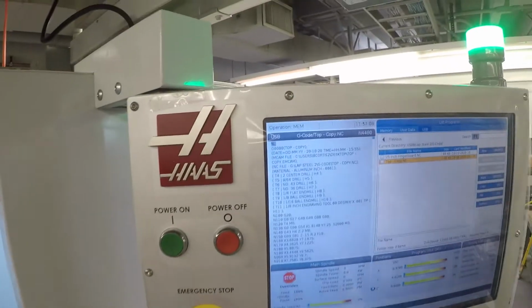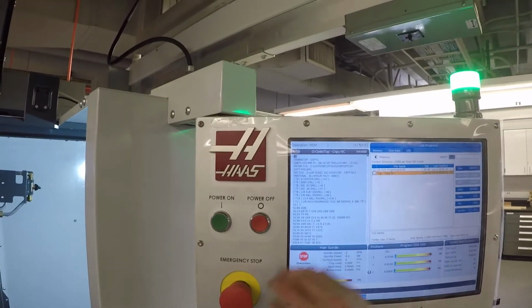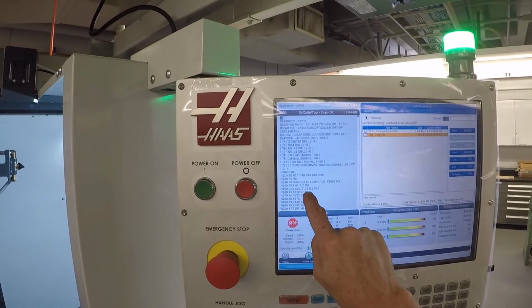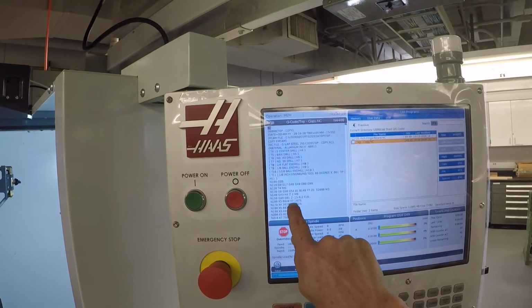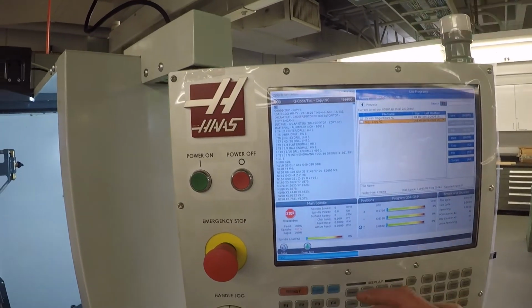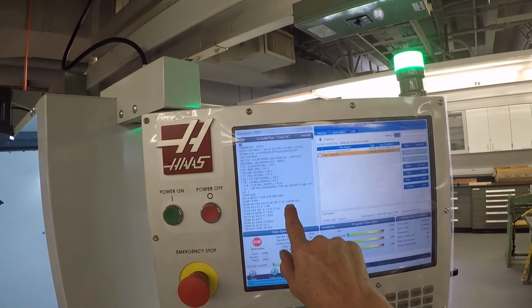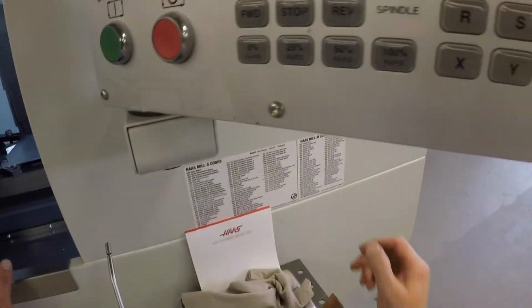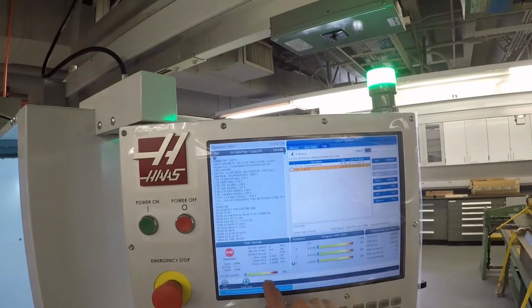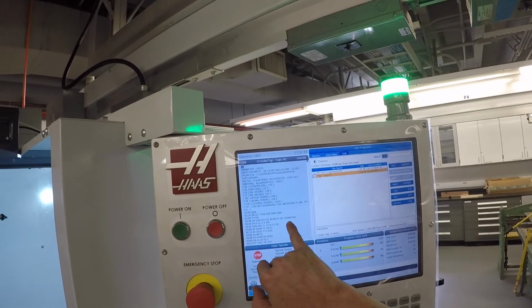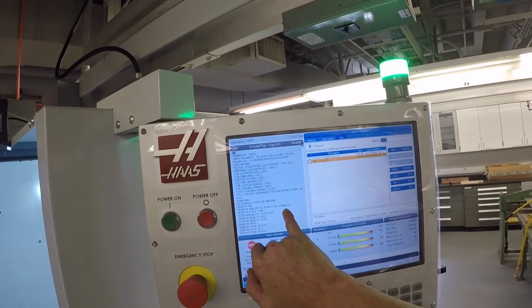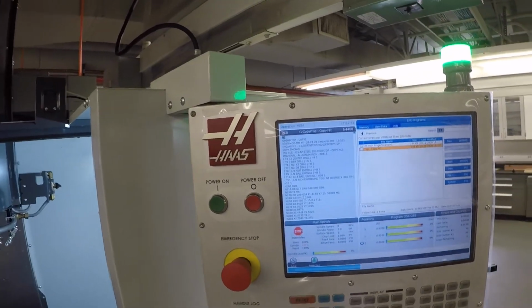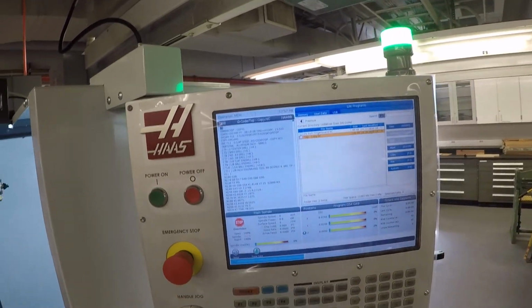It's going to run a cycle. It's called a CAN cycle, but I'm not going to get into it. Of drilling, of peck drilling, down to negative Z and negative 0.15, okay? You can see here, S stands for spindle. That's spindle of 2000. M3 is spindle on clockwise, I think. So it's telling the machine spindle 2000 on M3, which is clockwise, okay? That's all I'm going to say about the G code, but there it is.